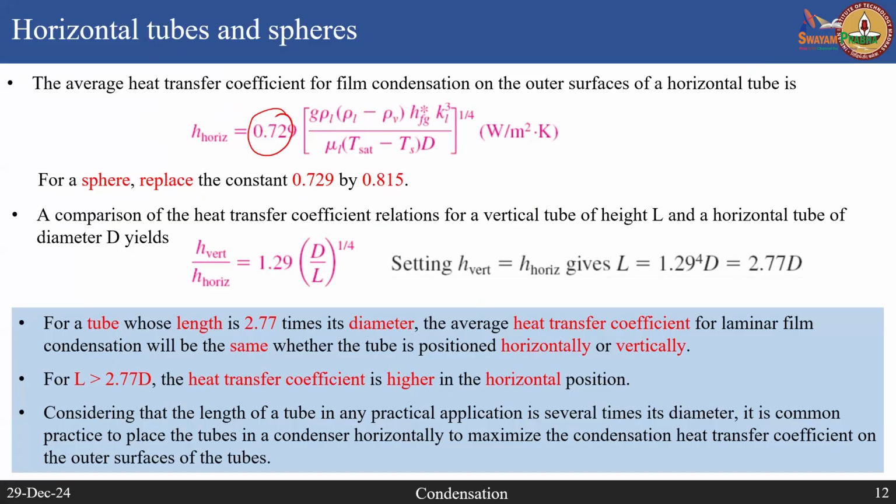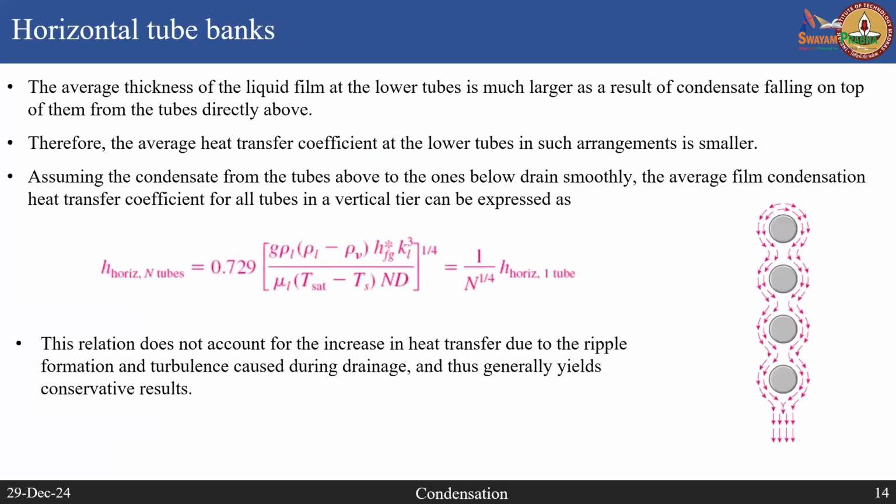So essentially there is no hard analytical expression when you change the geometry. So it is primarily developed for a laminar wave free regime for a vertical flat plate by Nusselt, and later on it was slightly tweaked or adapted to other heater configurations depending on whether it is a cylinder or a sphere.